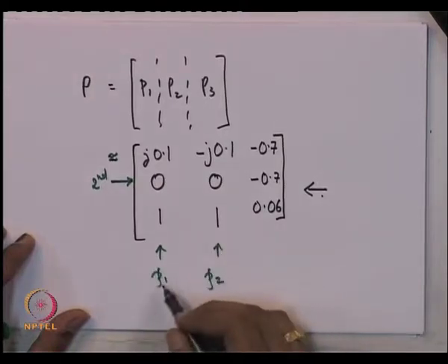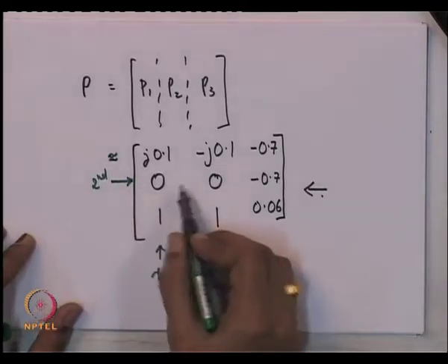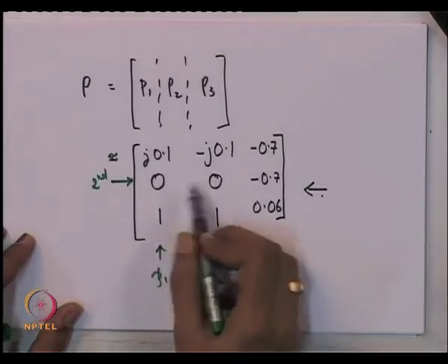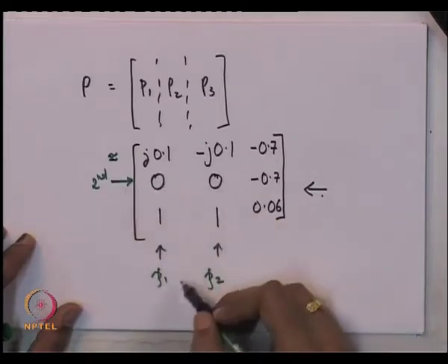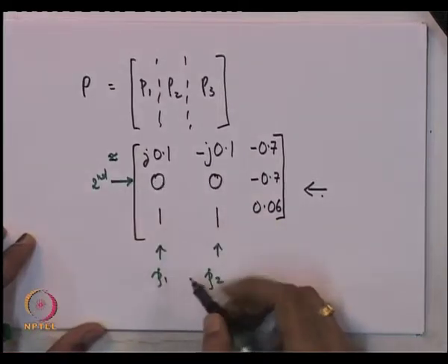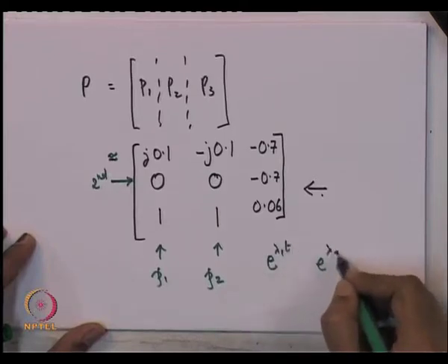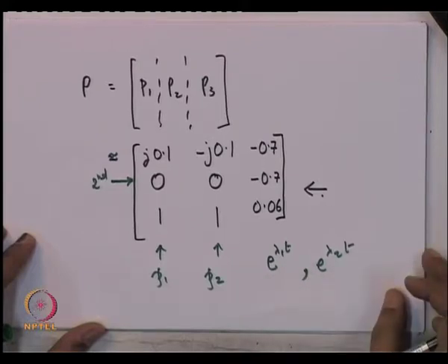These are corresponding to the first and second eigenvalues. These are in fact the complex pair. The second state has practically 0 observability. These were of course rounded off, but we saw that these were almost 0. So, you will not observe terms corresponding to e raised to lambda 1 and lambda 2 t in the response.